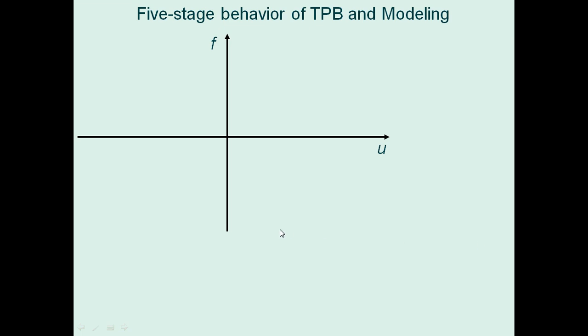A triple friction pendulum bearing can produce 3 pendulum mechanisms with 5-stage behavior. Under a small earthquake, the first pendulum mechanism is formed with high stiffness. The second pendulum mechanism with moderate tension stiffness is formed under a moderate earthquake. The third pendulum mechanism is formed under a strong earthquake. The tension stiffness of this pendulum mechanism is small so that the isolated structure and its contents are protected.